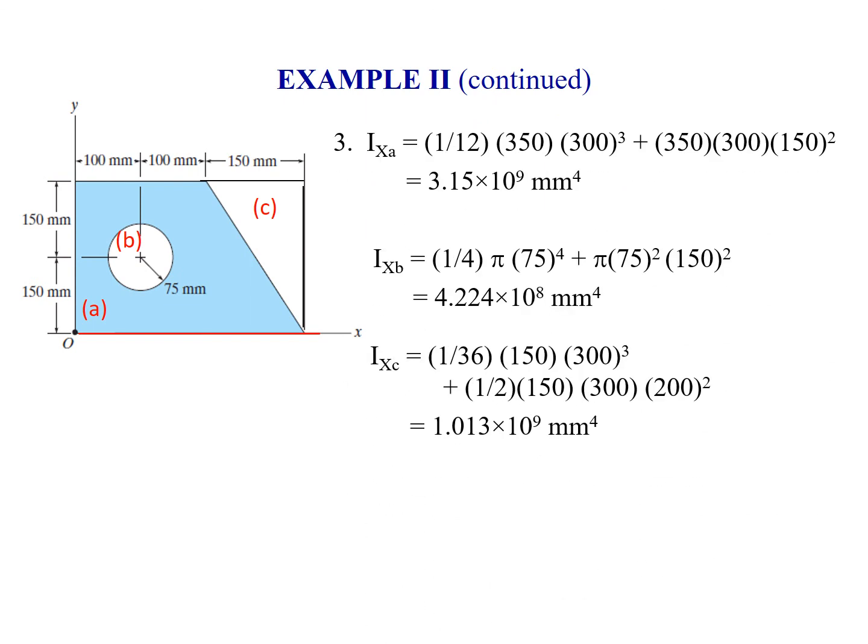If we calculate the moment of inertia contribution from each of these areas, we get the equation shown, where we're just looking at the individual calculations that come from the inside cover of the book. I want you to know how to use those tables, but I don't want you to have to memorize any of those tabulated formulas.